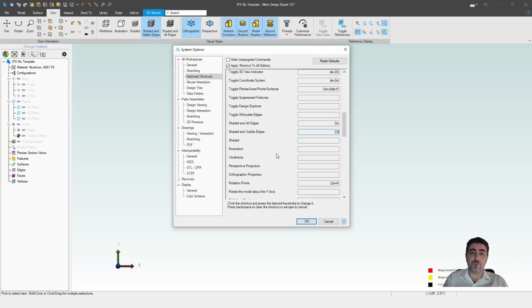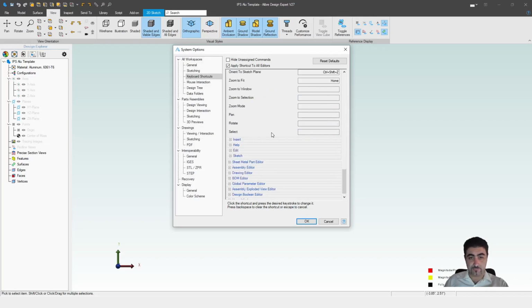You can select obscured edges for fillets, chamfers, constraints, and whatever. Okay, so really, really important because this very shortcut key is a keyboard shortcut or hotkey or whatever. This is what allows you to select edges for fillets and chamfers that are behind the current surface, that are obscured. So these two, immensely important. And yeah, the rest I don't think I've changed.